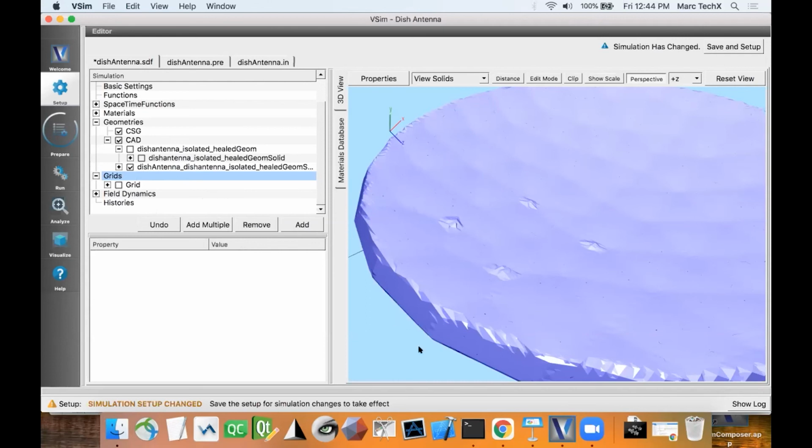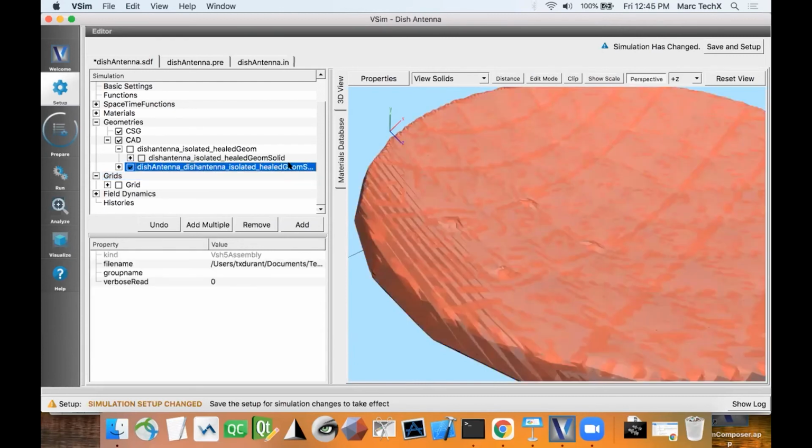And one thing that I will also share is that you may try to create the cut cell mesh and your geometry may not really be compatible for some reason. For example, if you had a mesh with holes in it, or it's malformed in some way, in which case this new surface would not have appeared. And instead, you would get a warning message in the log.